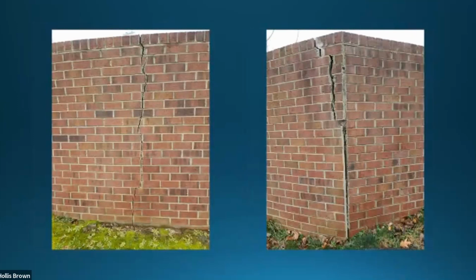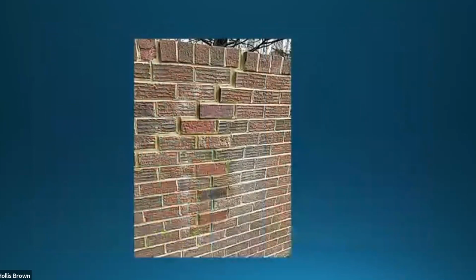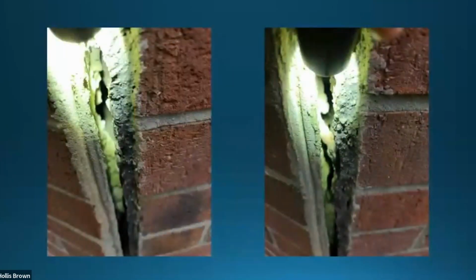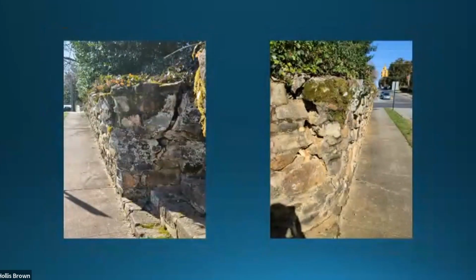So this is a concrete, or obviously a masonry foundation, but behind it is a drain. There is a drainage system, I think, on this one, but it's flat grade. They didn't tie the brickwork together at the corners at all. And we're going to find that there's no core fill, no horizontal joint reinforcement. This wall wasn't even 5 years old. It's probably 4 or 5 years old and it was failing miserably. No core fill insulation, the brick aren't tied together. Whoever put it up should have been shot.